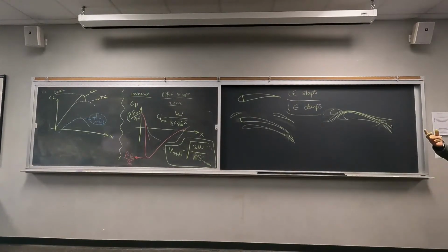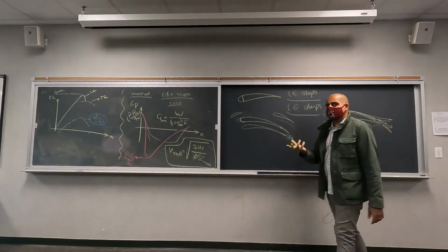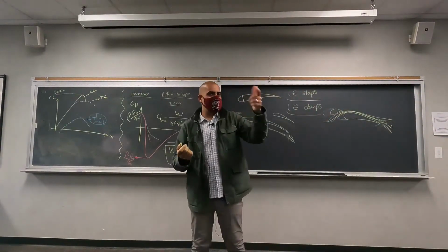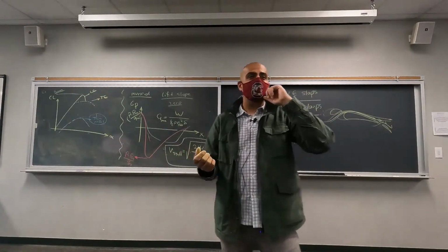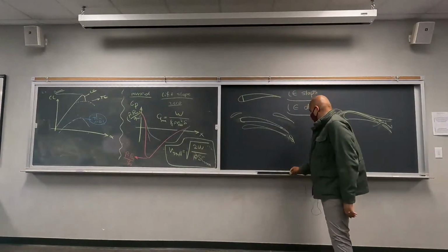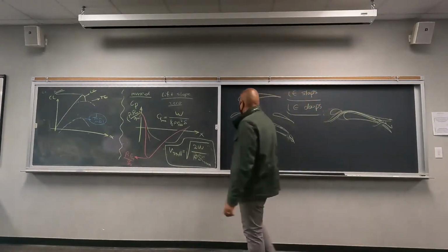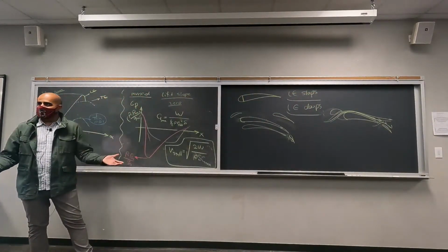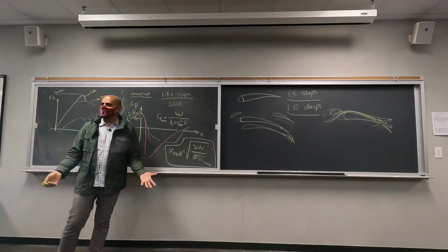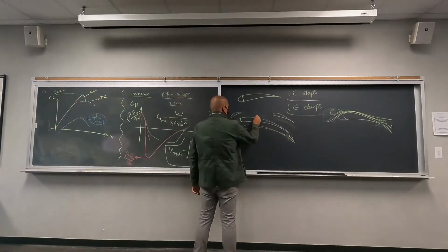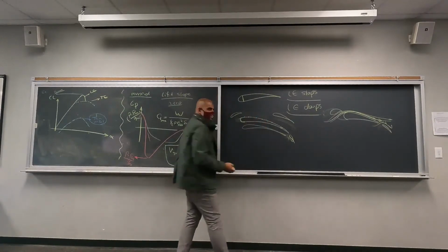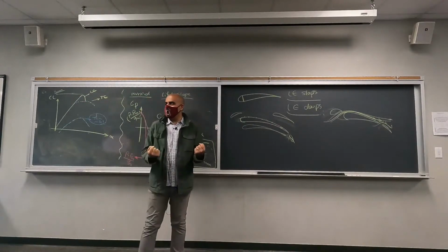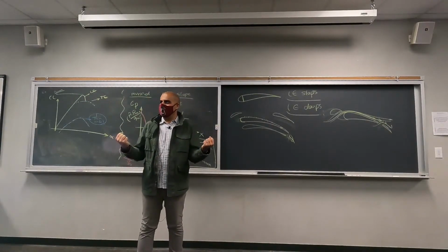There are other mechanisms. This is worth mentioning as well. This is actually something that some people did some research with, like the dielectric barrier discharge. Ben brought that up. That's something that you can definitely have. You're going to ionize the gas on top, which is going to introduce an electric field in the system. That's an extra source term in the Navier-Stokes equation, an extra force going to push the flow down. But you can also have suction. We can suck the boundary layer in. When you're sucking the boundary layer in, there's no space left for the flow separation to happen.